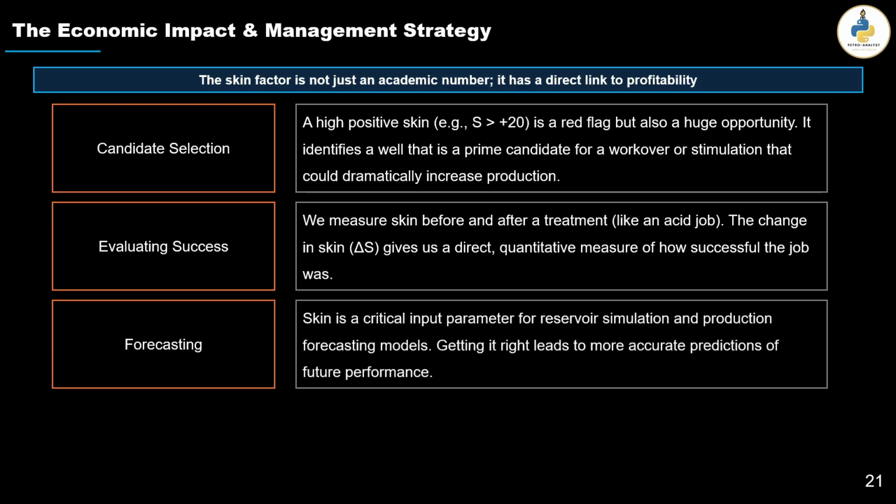Forecasting: the skin factor is used in any model, either a simple well model like in Prosper or PipeSim, or for reservoir simulation. So getting the right or the actual skin factor makes the model more accurate. Getting the right value of the skin factor will make it easier to get accurate predictions for the future. The life cycle can be summarized by this.